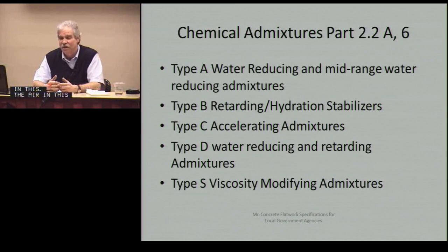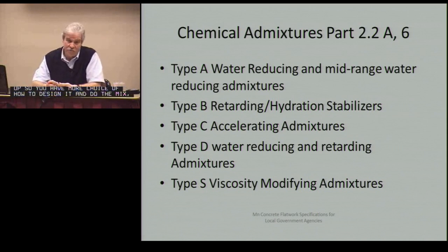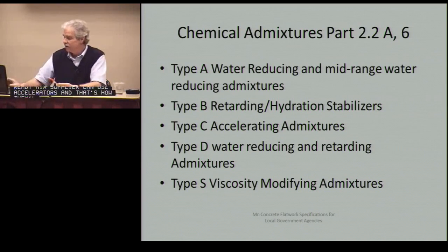We tried to follow the DOT specifications so you wouldn't have to relearn things when you get on one of these projects, but we tried to open it up so you have more choice of how to design it and do the mix, like the accelerators here. The ready-mix supplier can use accelerators, and that's how they'll get their early strength concrete mixes to get the McDonald's driveway open for tomorrow.